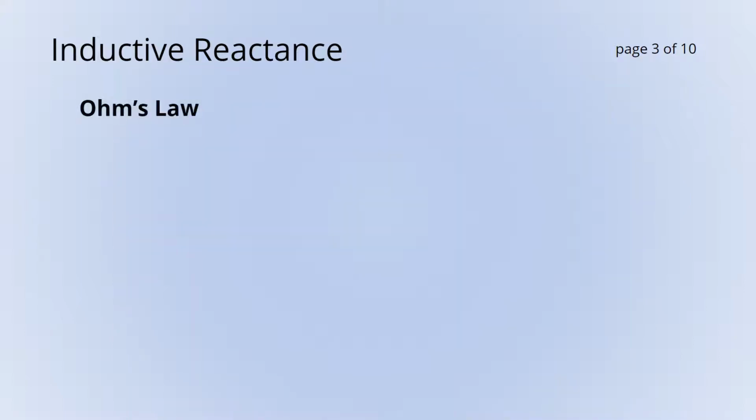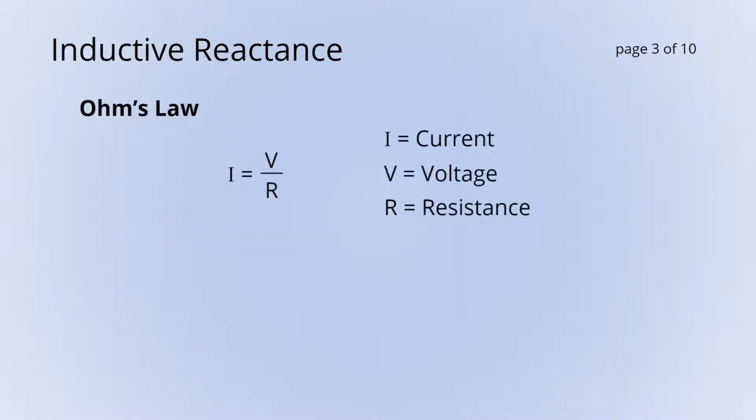Ohm's law: current equals volts divided by resistance. Using Ohm's law, if there is only 8.5 ohms of resistance plugged into a 120 volt wall socket, there will be a 14.1 amp draw, enough to trip a 10 amp circuit breaker.